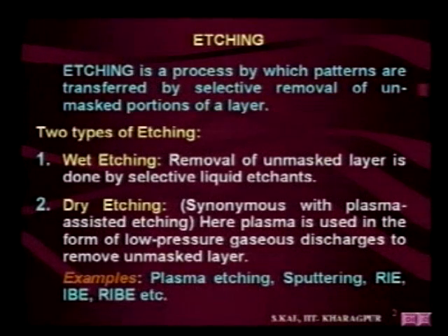In both cases, means in case of wet etching and dry etching, a reaction will take place between the etching medium and the film. A chemical reaction will take place between the etch medium and the film to be etched, and the reaction product should be such that either the reaction product evolves as a gas or the reaction product is soluble in the etch medium.